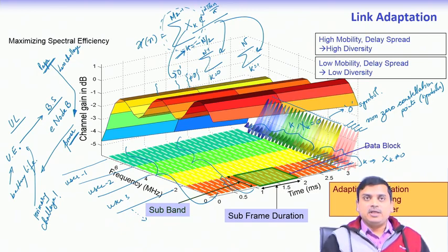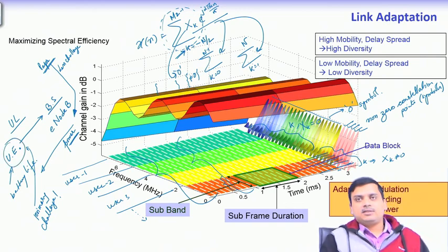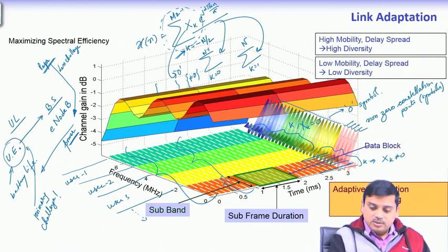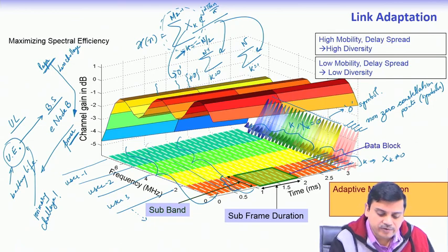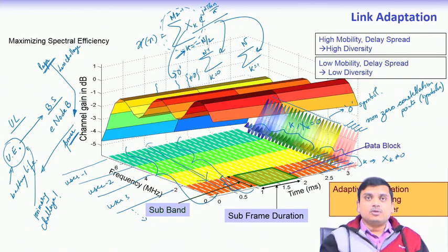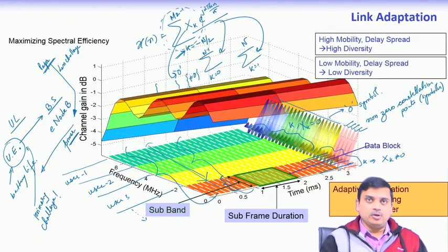In the 4th generation, the uplink has a solution at the user end, in the downlink it does not address it at all. And since we have also said now that in the uplink the user equipment need not be sending across the entire band of frequencies, that also helps. So, in the 5th generation, although it allows for DFT spread in the uplink in order to save power, it can also allow OFDM transmission in the uplink direction. Yeah, this is something one has to note very carefully.